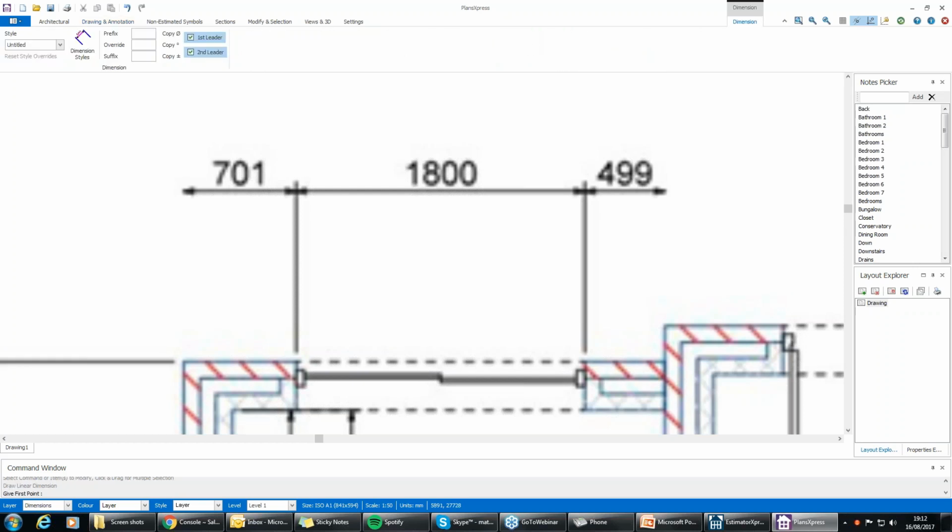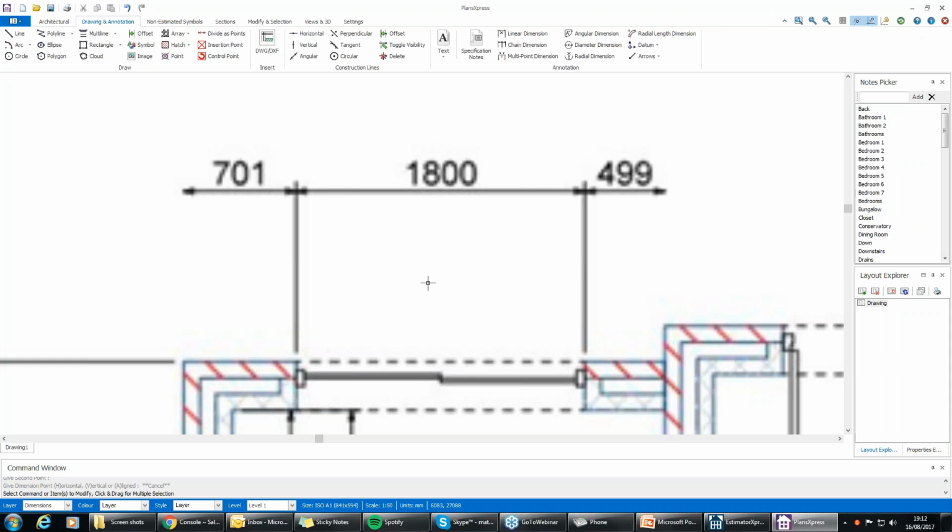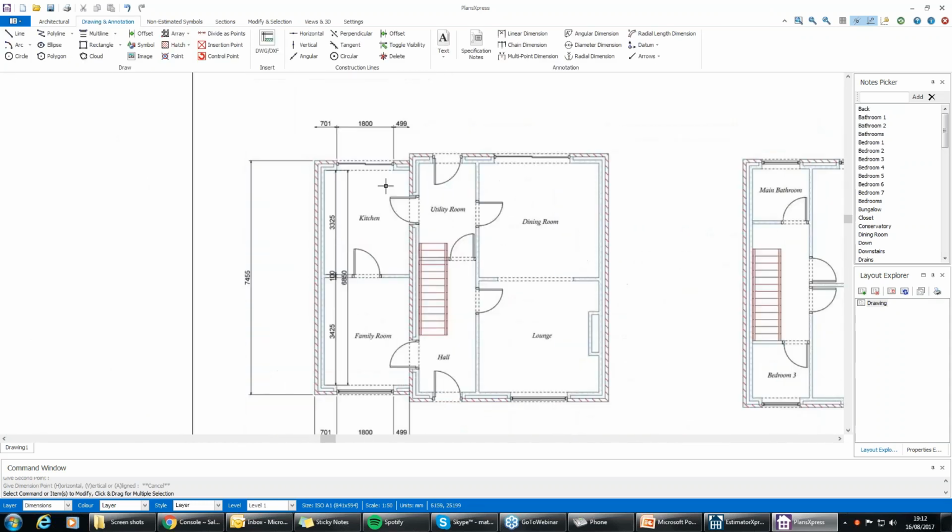Okay, so I can click the linear dimension, I can find the line here, and then what I can also do is make this... it's going to be longer if I start moving it up or down, but if I hold the shift button, that becomes dead straight. Okay, I can't mess that up anymore. And then I'll find out what this line is, and it's telling me that I'm 1 millimeter out. Okay, and 1 millimeter over the grand scheme of an entire job, that's not going to be a lot missed. Okay, so I know this is going to be the correct scale.